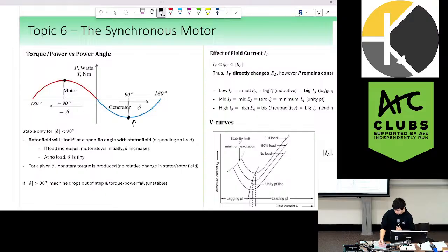Personally, I think it's a little silly to include the extremities of this graph, just because if you were to ever hit that kind of portion, it's because there's been a small deflection of your motor in an instant, where rather than being a fixed phase away from the field generated phase, you get knocked back physically by a certain amount, and then the torque would still be able to bring you back to a certain phase difference.